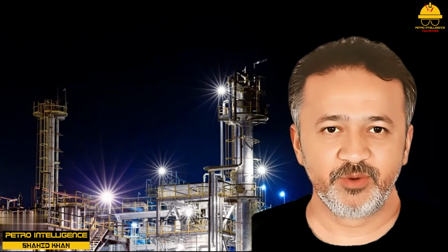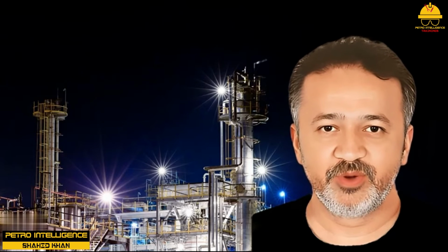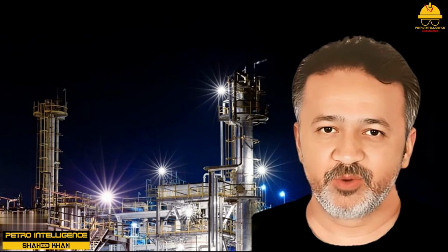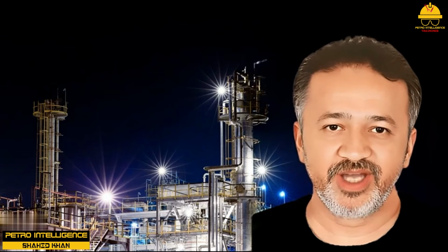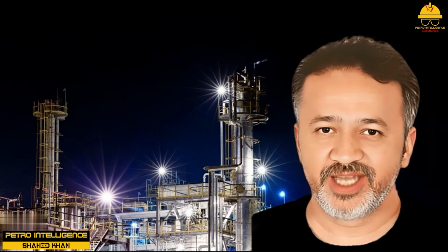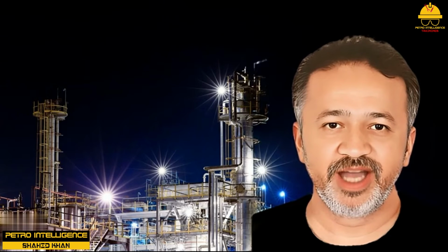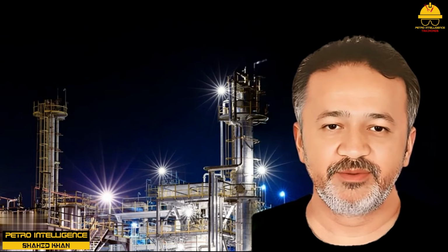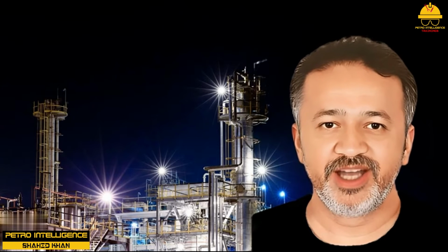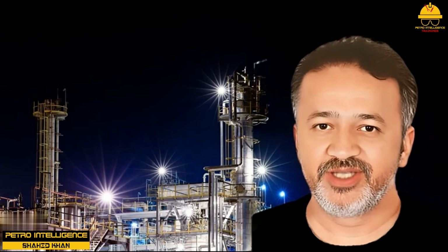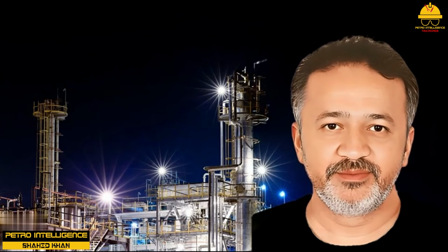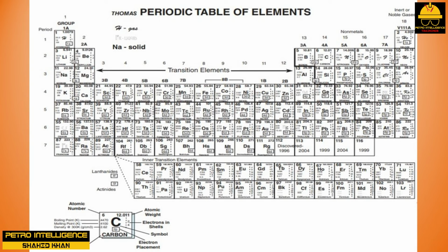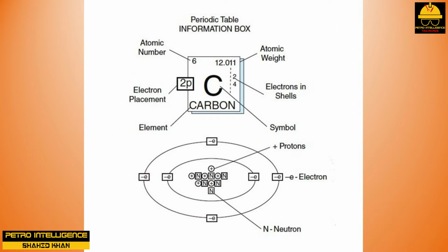Exothermic and endothermic reactions. Exothermic reactions are characterized by a chemical reaction accompanied by the liberation of heat. As the reaction rate increases, the evolution of heat energy increases. Controlling reactant flow rates, removing heat, or providing cooling can control exothermic reactions. This type of reaction is subject to runaway if sufficient heat is not withdrawn from the system. Endothermic reactions absorb energy as they proceed. They must have heat added to form the product.